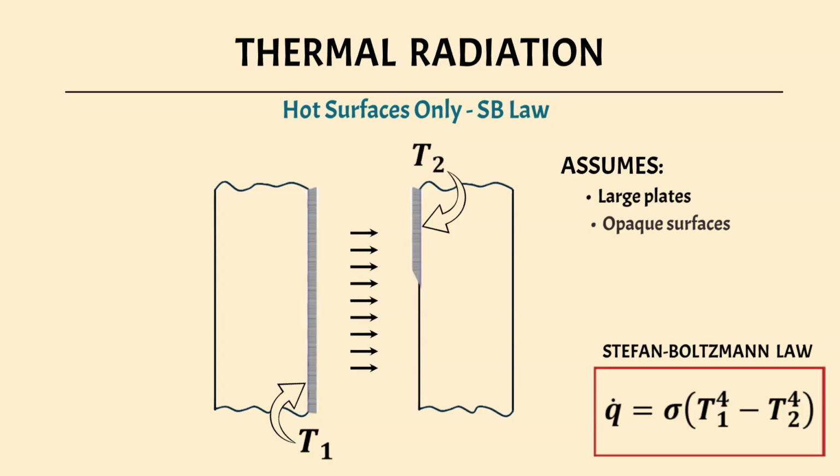In such cases, a surface coating can be used to render the material opaque. Such tailored coatings can significantly alter the surface properties, enhancing or suppressing heat transfer without needing to replace the entire object. This ability to tune emissivity is a unique and practical aspect of radiative heat transfer.